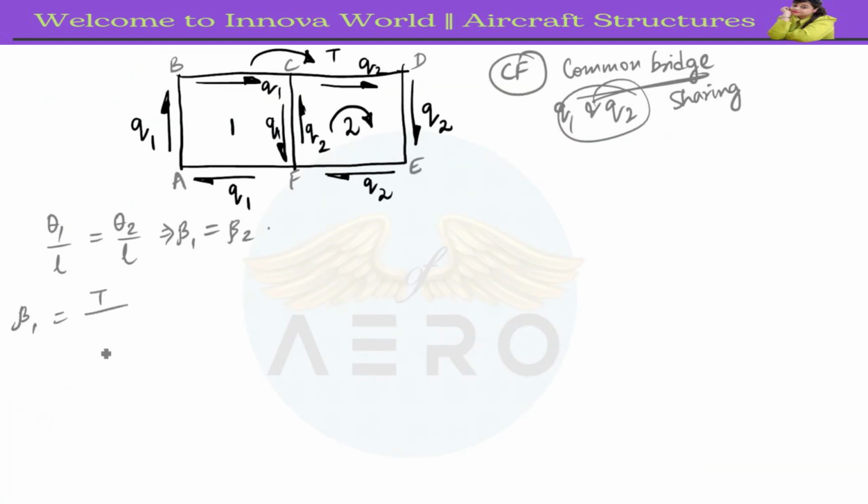So theta equals T by 4A squared G, closed integral ds by t. Okay, this was the formula. Now when I am taking theta 1, that means I am going to take T1, the torque that is acting on cell 1, and A1, the area of cell 1.